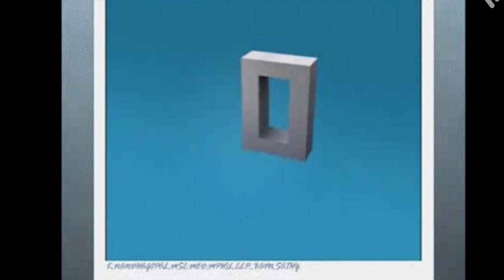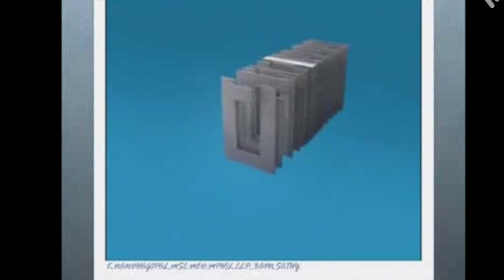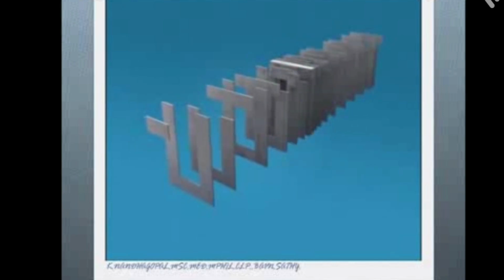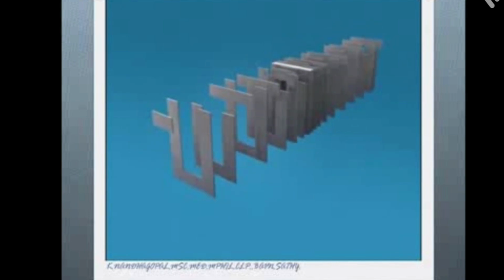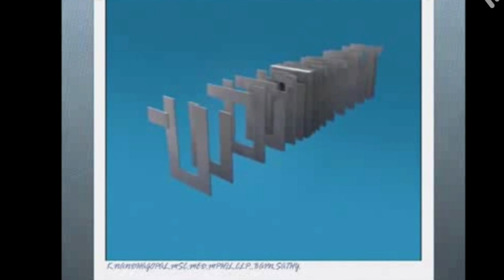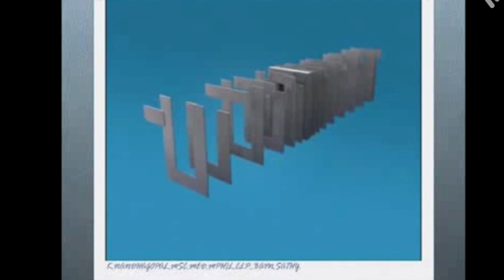The coil is wound over a metallic frame. It's made of metal, which increases the magnetic flux. Insulated sheets are there. Already you know about eddy current. Due to eddy current loss, to reduce that, insulated metal sheets are used in the transformer.